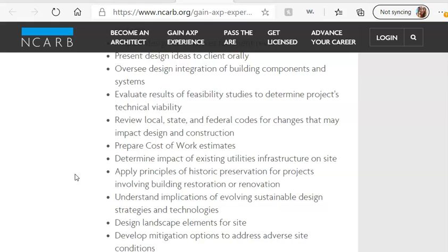And then you will prepare all the stuff for landscape. How do you make sure that people can safely get into the building per the accessibility guidelines? And you will design how everything will function to make sure that the building going forward has the appropriate egress ways, the appropriate rated wall assemblies for escape, that the building won't come down or kill anyone if a fire or an accident was to occur.